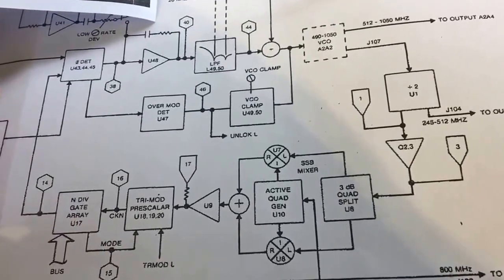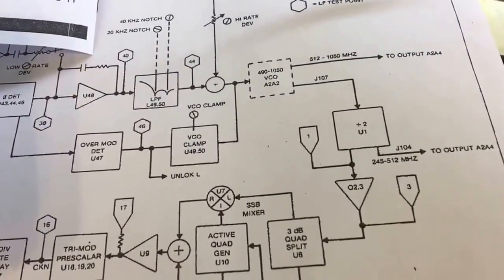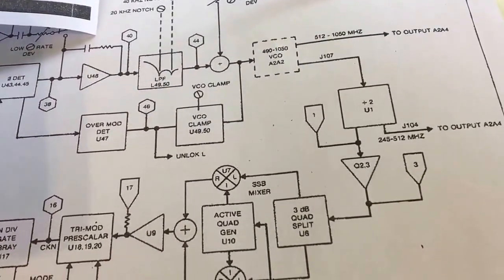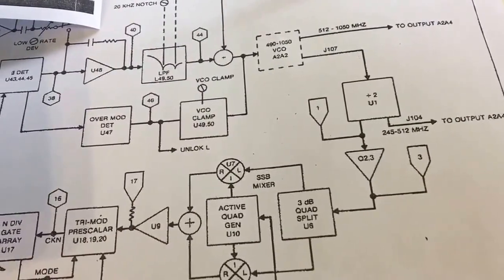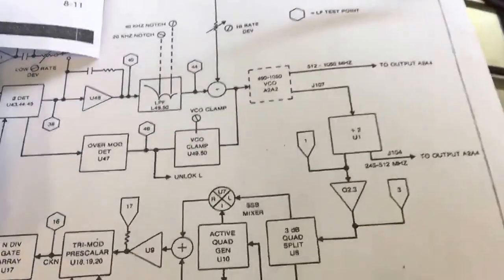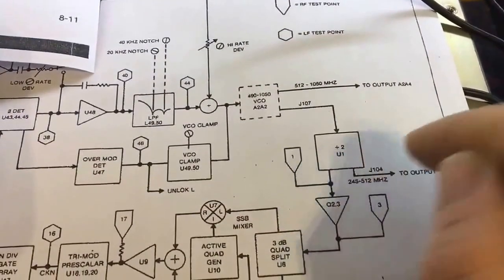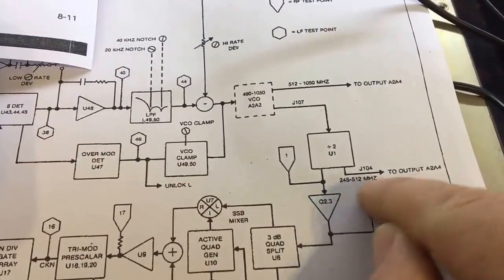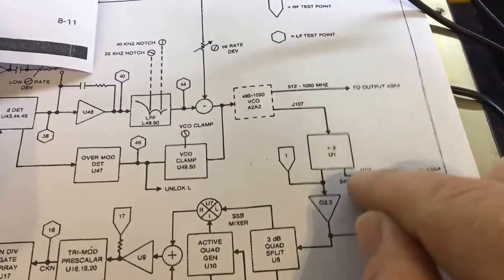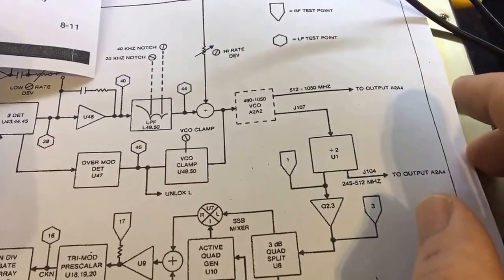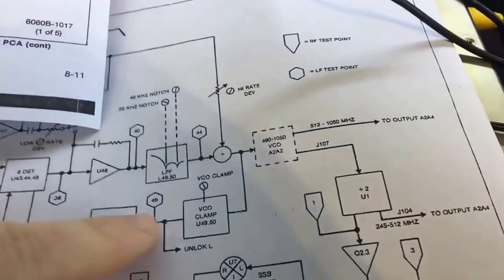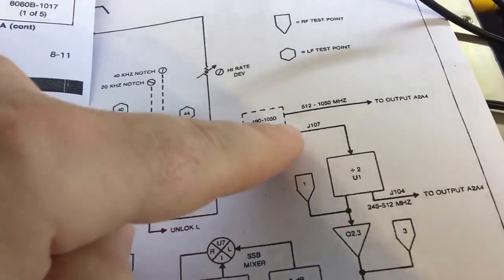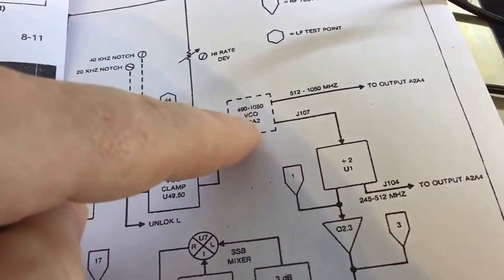So actually there was a point I did see a 10 MHz offset. I did mention it earlier on. So maybe that is related. If it's halving, because there's a divide by 2 here. So it might have been that band I saw that 10 MHz difference. That's possible, isn't it? Certainly is possible. Anyway, so that's that VCO there. That's that VCO output. The main VCO.